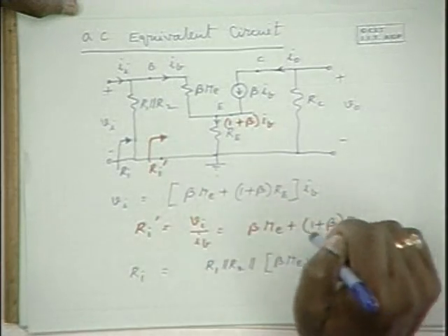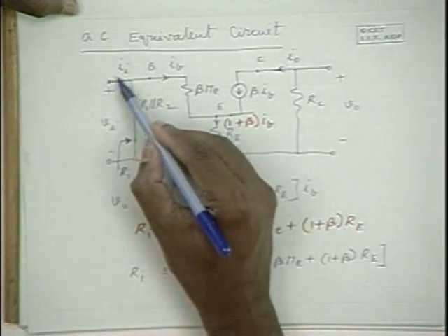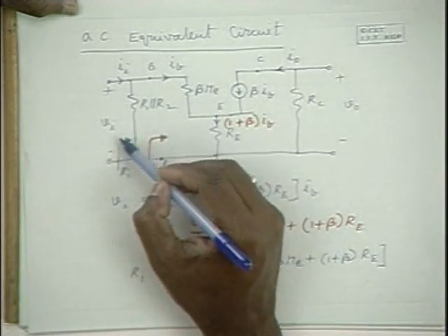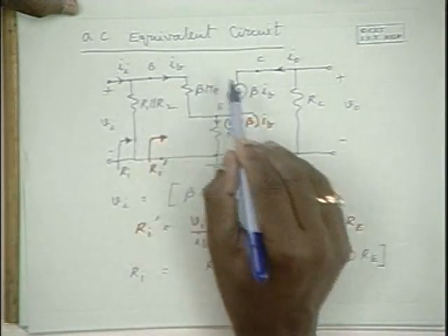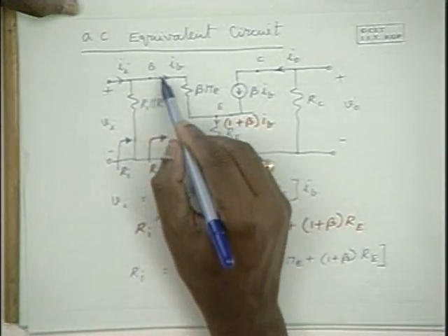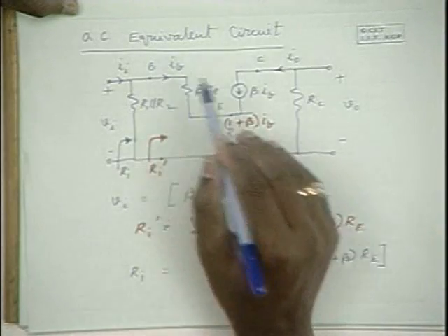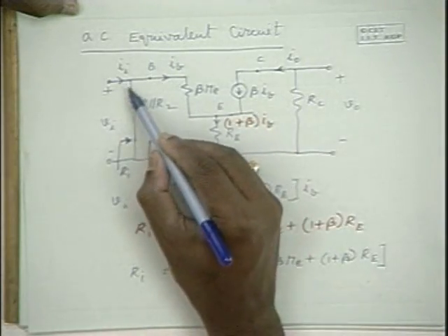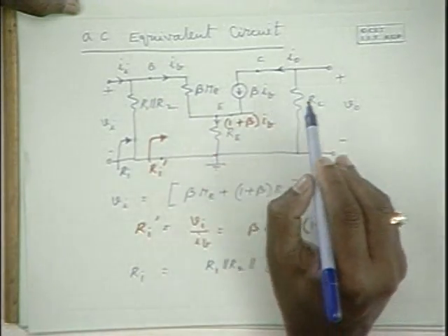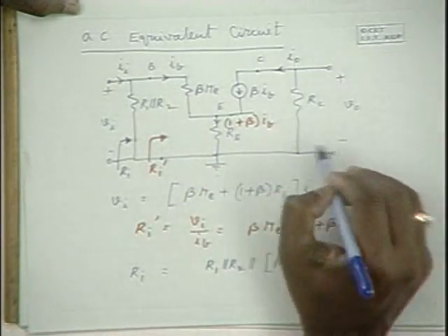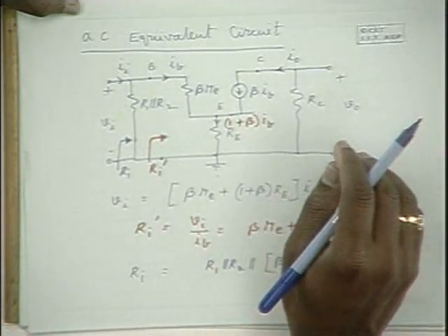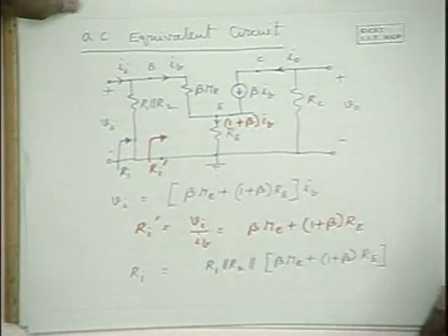We know the expression for Ri dash. Or if we know Ii into Ri. So please note that Ii into the whole of Ri, the whole input impedance, is equivalent to this IB into Ri dash itself, because there is no series resistance here. So hence we shall substitute this expression and this expression in the voltage gain expression and get the result.